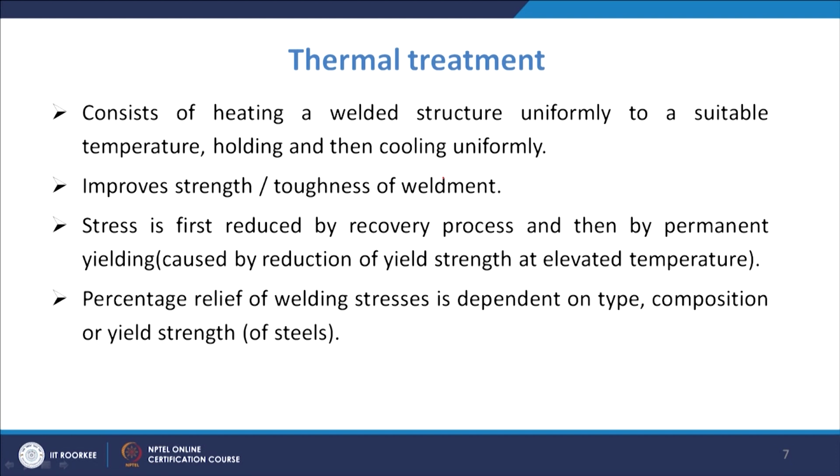You will have to select the temperature appropriately, and also the time for which it is held. That results in a percentage relief of the welding stress, and it will depend upon the type of composition, how much is the time of holding, and what is the temperature.